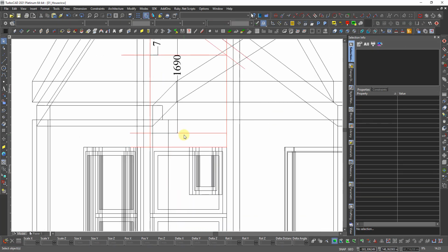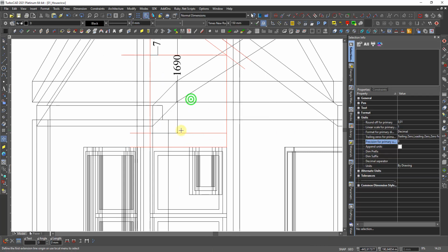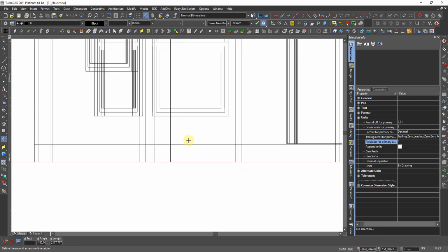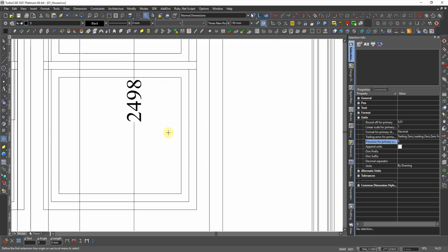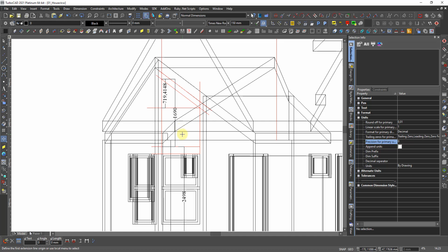And then on this window, I take also measurement from nearest and down to the bottom of the wall, to down here, then nearest, and I have that. That is the insertion height, 2498, if I use the bottom. So then I insert a window there that is 1.7 by 1 meter at this height at the bottom.